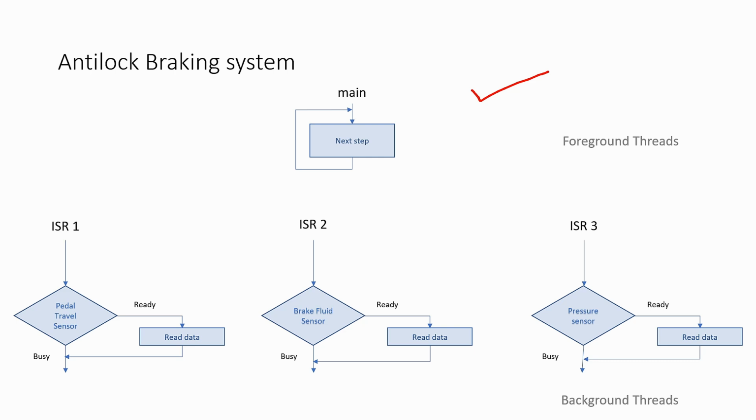But here also we have a problem: most of the time will be spent in the main function rather than in the ISRs. The ISRs will be called only when the sensor data is ready, or only when the particular time period for the ISR is allocated. So most of the time will be spent in the main function. This is the main drawback of this particular multi-threaded approach.